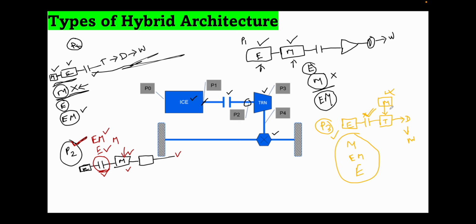architecture. But based on my understanding, if you are placing the motors with the transmission, the structure will become a little bit complex, and the control strategy will also be complex. So this will be a little bit complex architecture and hard to operate. You need a good control logic, but here you are able to minimize the losses coming from the transmission side, and you are providing the most efficient torque production in this type of architecture.